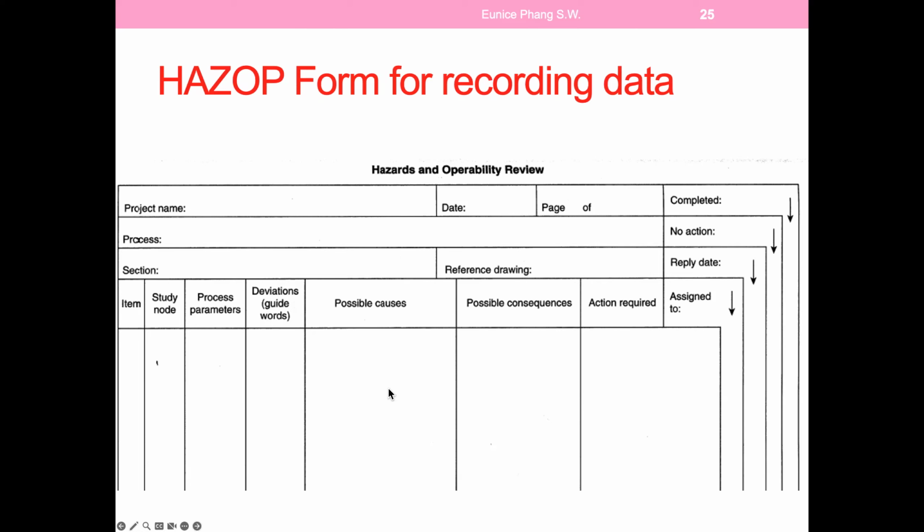So for every guideword you need to have at least one to two possible causes, and what the consequences are when you have no flow rate or a higher flow rate. That's where you want to see: is this bad, or is this something I can ignore? Is the risk worth taking if I'm not taking any action? Okay, what we will focus on a lot is this part, the actions required. You get a lot of marks on your actions here.